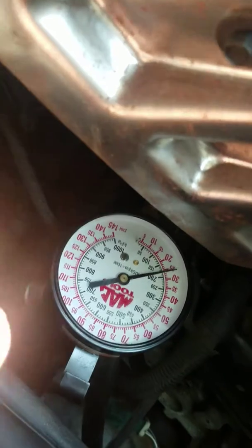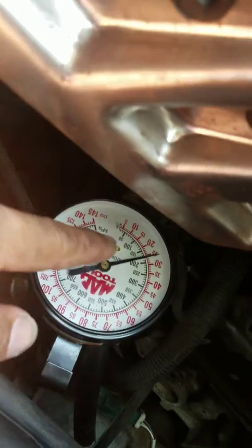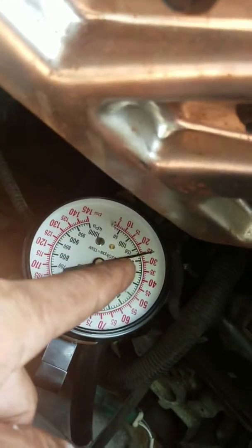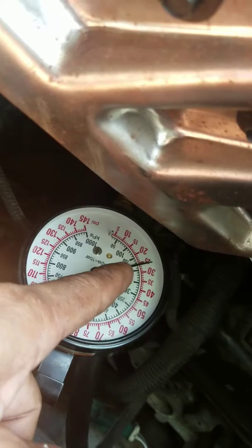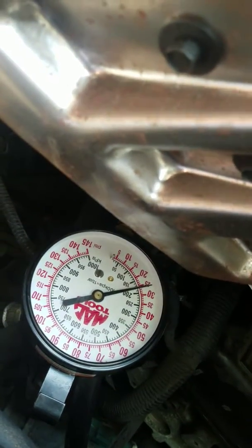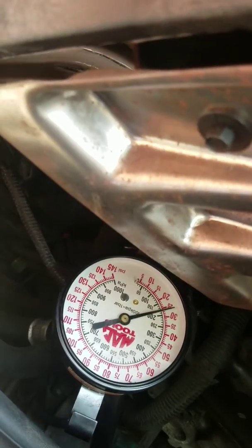I check my fuel pressure at idle and when the car is off. When the car is off, I get 20 psi, and when it's running, I get about 26. It is way below the specs. I don't remember the specs, but you can look it up. But this may possibly be because of a bad fuel pump, they replaced the